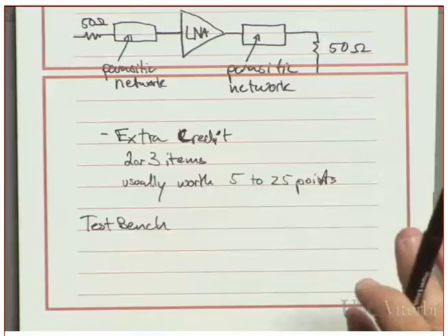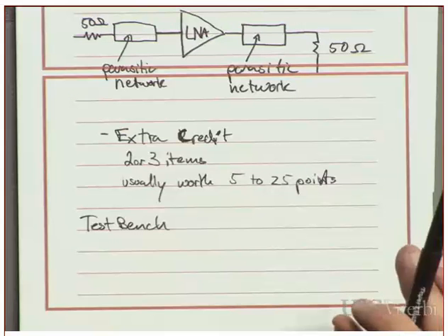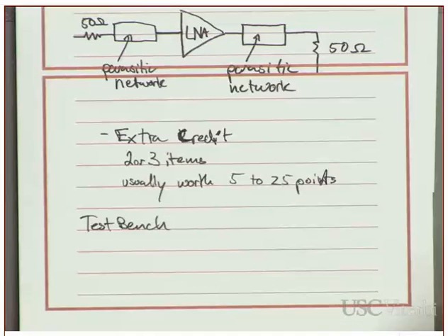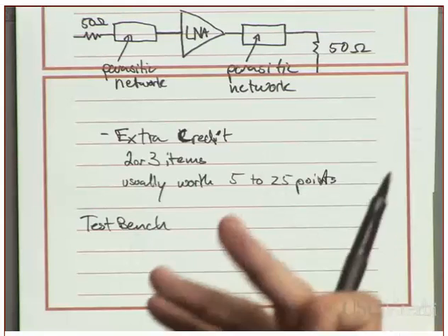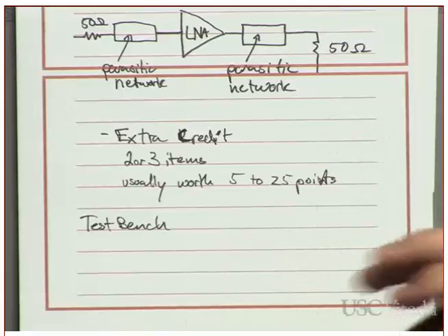There's always one or two groups who really want to do a double-ended mixer or a balanced one. And that's fine if you really want to do that, but that's kind of on your shoulders. Because in order to do that, you do have to design a balun for the frequencies that you're going to have, and then you have to recombine the signal at the output.